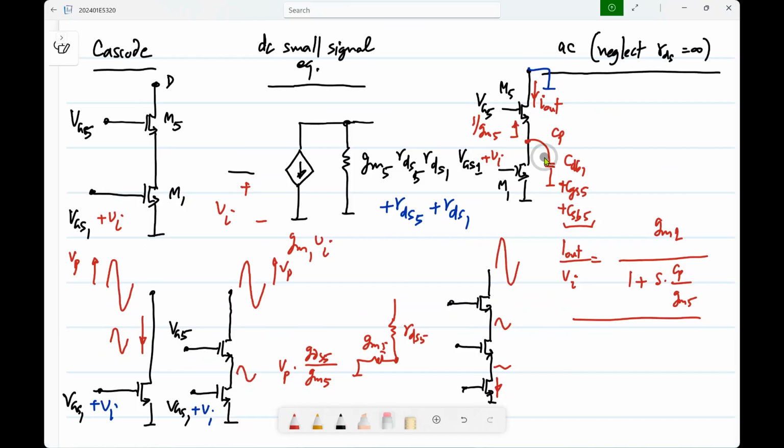Anything else? This part is okay. So every cascode node introduces a pole. Like everything, it comes with a cost. First is the swing limit, the other is these parasitic poles and so on. Now again, if I put the entire op-amp and try to evaluate the transfer function, it becomes very messy. So roughly speaking, you can assume that every cascode node introduces another parasitic pole of the order of that parasitic capacitance divided by GM of the cascode device. Okay. Is that fine?